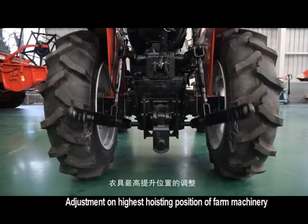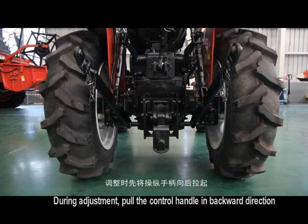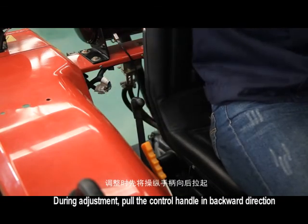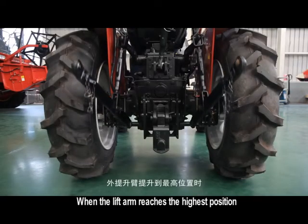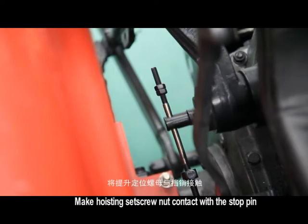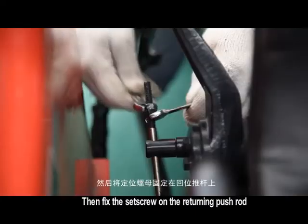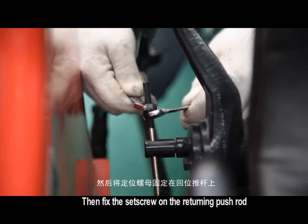Adjustment on highest hoisting position of farm machinery. During adjustment, pull the control handle in backward direction. When the lift arm reaches the highest position, make hoisting set screw nut contact with the stop pin. Then fix the set screw on the returning push rod.